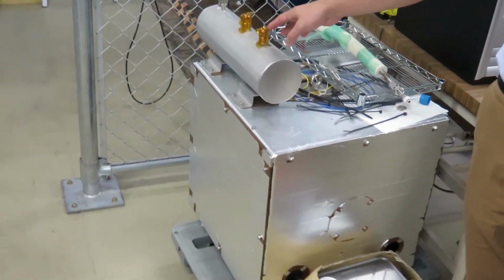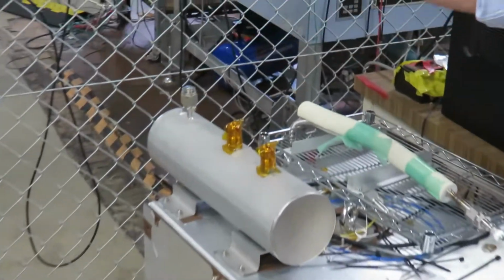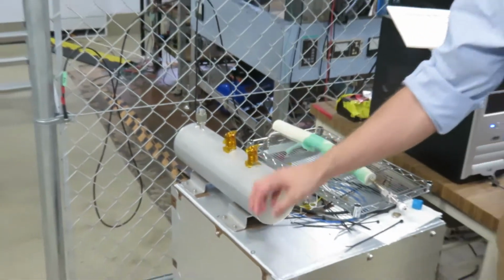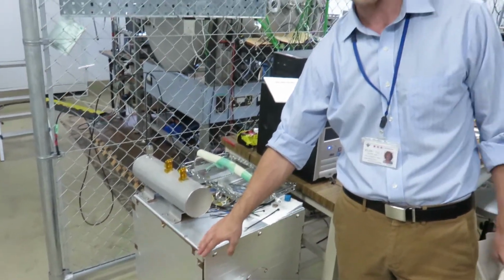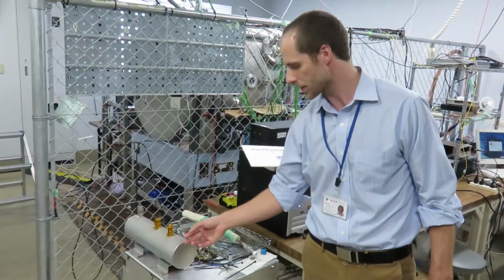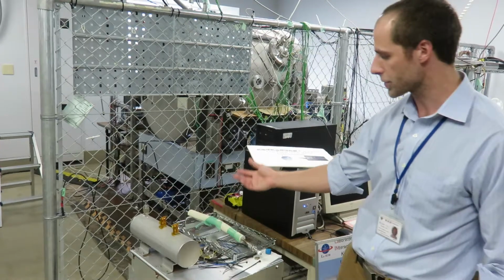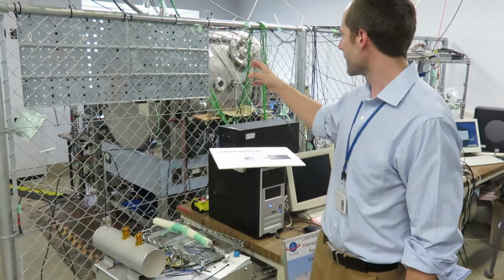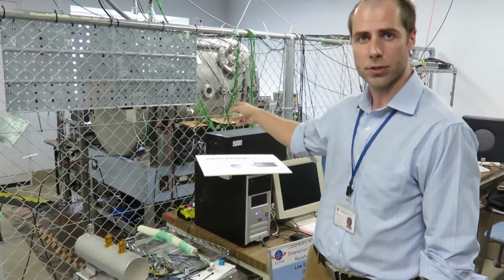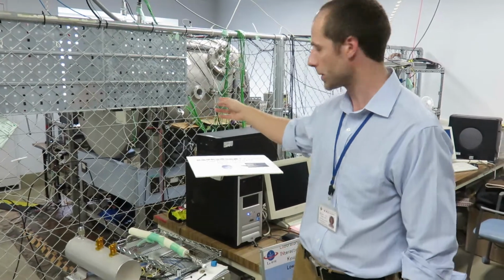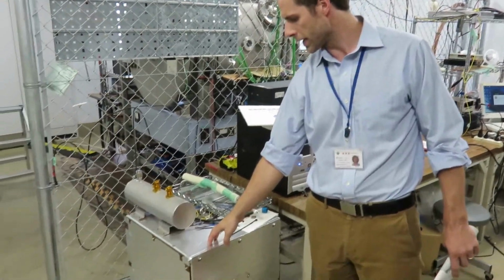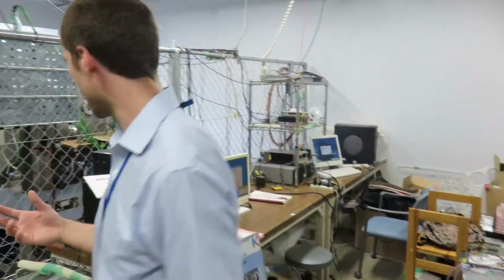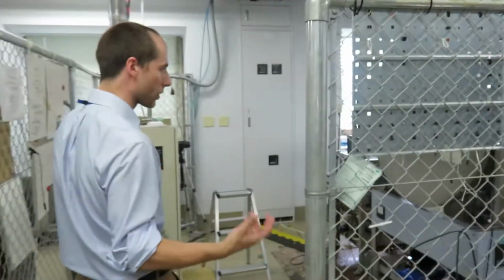We flow liquid nitrogen in, and liquid nitrogen comes out, and it evaporates into gas in the room temperature. But inside the chamber, we can reach very low temperatures and thermally cycle, in some cases, our payload, which could be a solar cell or something else. Additionally, we have installed a lamp that we use to simulate the sun inside this chamber. So if we put a solar cell inside, for example, we can have some temperature control and also a solar simulator to introduce some IV curve to measure solar cell performance.